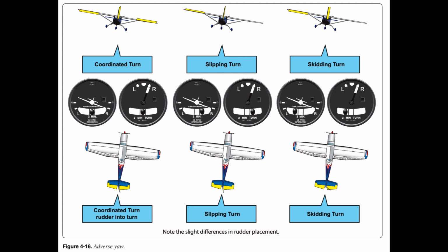Another problem in turbine engines is the icing of engine probes used to set power levels, for example, engine inlet temperature or engine pressure ratio (EPR) probes, which can lead to erroneous readings of engine instrumentation, operational difficulties, or total power loss. The type of ice that forms can be classified as clear, rime, or mixed, based on the structure and appearance of the ice.